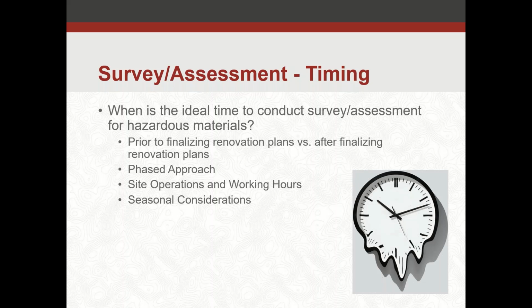But on the flip side, when you're looking at a vapor intrusion assessment, when you're looking at radon or indoor air quality concerns from volatile organic compounds, your colder winter climatic conditions are better to assess. That's going to give you a worst case scenario, being that the buildings are going to be closed, more tightly shut up during those wintertime conditions, and you're going to have snow cover and such. That's going to give you a little bit more of a stack effect to bring that material in through the interior environment than out through the exterior ground surface.